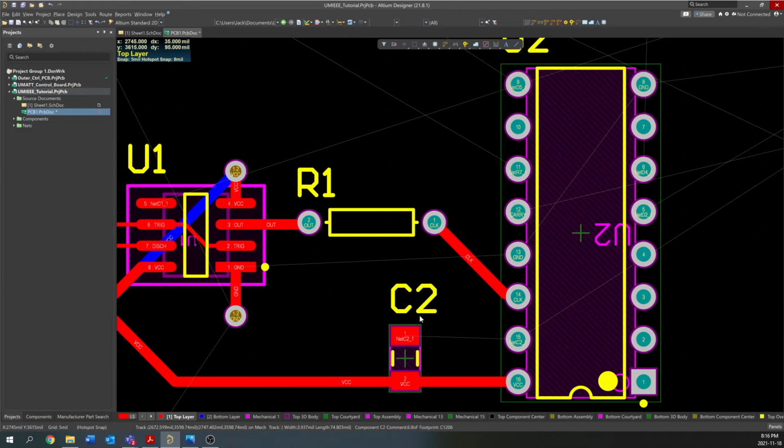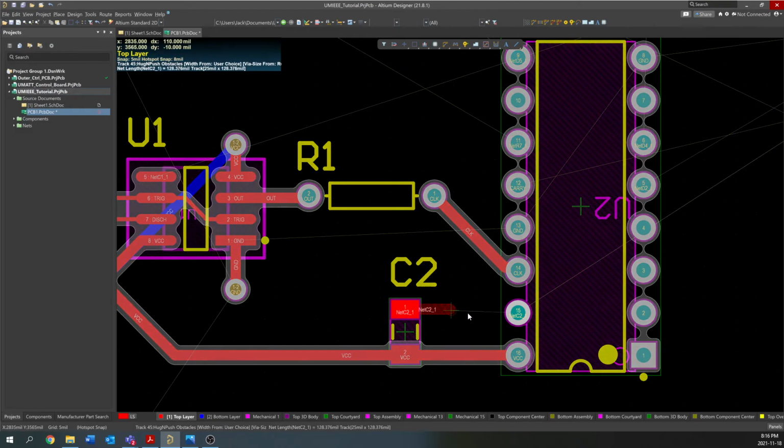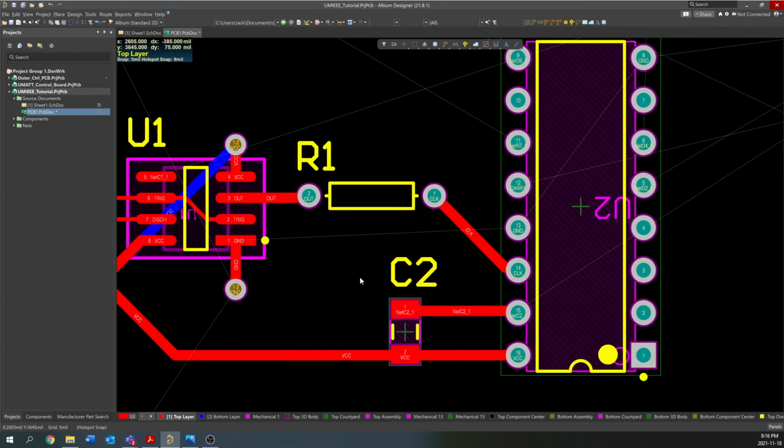That's for some applications. High power applications, I wouldn't necessarily do that because you could have a bunch of heat going into a component, but this counter is going to be drawing a pretty small amount of current, I would imagine. Even though it's driving those LEDs, it's not going to be pulling maybe more than 70 milliamps or maybe 100 milliamps, I would guess. So that's acceptable in this case for a 25 mil trace. I'm going to connect those two nets there.